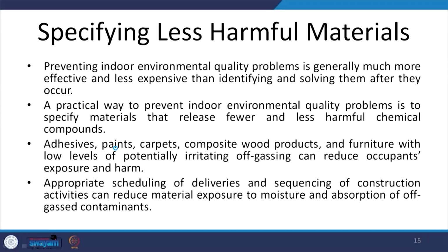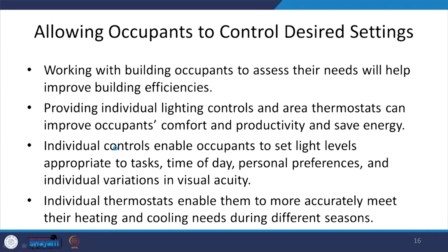Now, how can we do that? Besides the design of mechanical systems and ventilation systems largely, we may also specify less harmful materials, materials which have less VOC, zero VOC ideally, but at least lesser VOC generation. So, proper materials should be specified in building construction. Another strategy, which is not a design strategy but a maintenance and operation strategy, is to allow occupants to control their immediate environment to the desired settings.